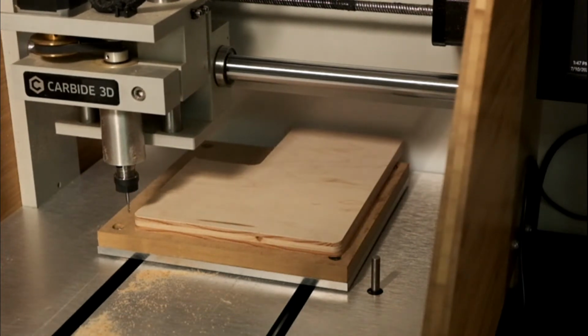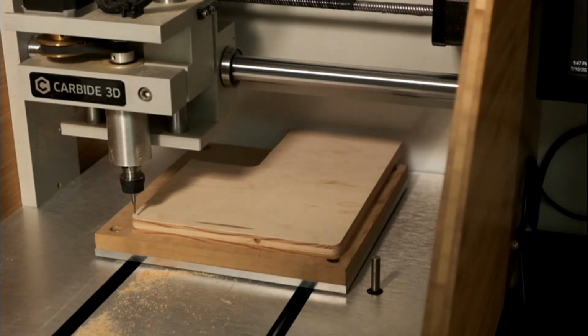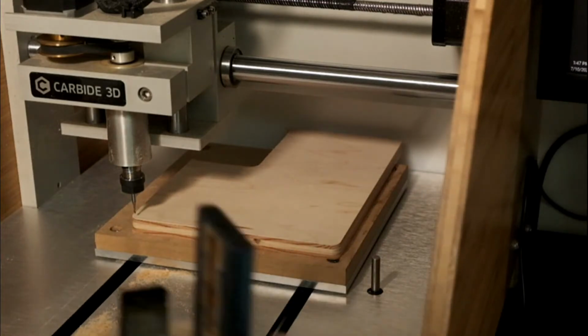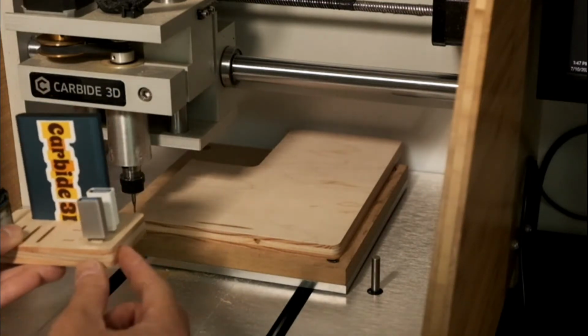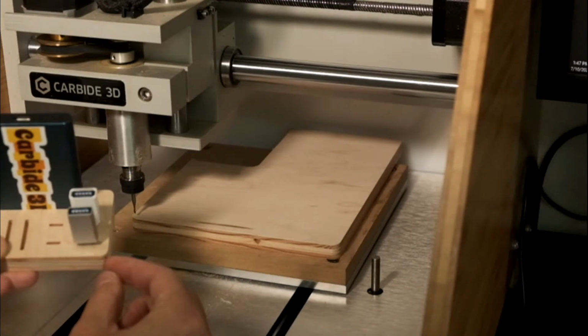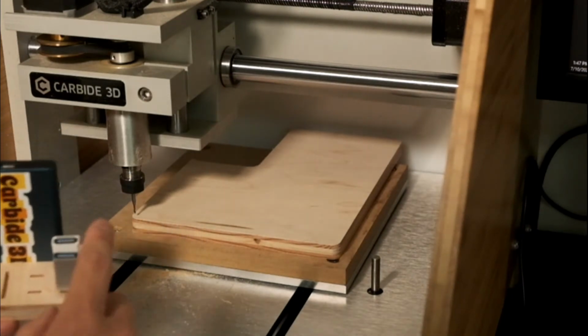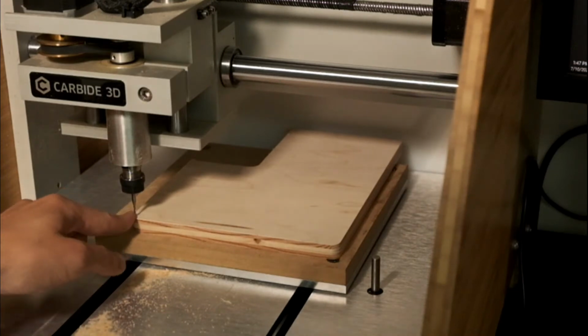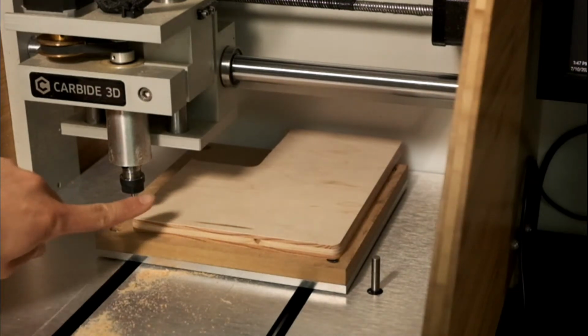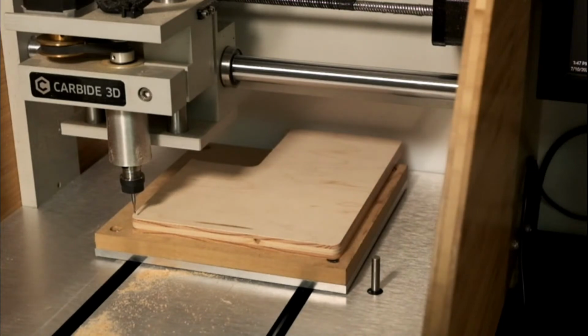And we're going to go right about there for my X and Y zero. Because this piece has a radius here, the corner of the bounding box is actually a little off where it's not going to be over your stock. So even though I'm sort of over this radius, I know most of the piece is going to be inside the stock that way. So I'll just set my X and Y zero. Zero those out, and then let's load the toolpath.